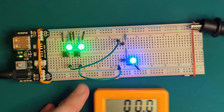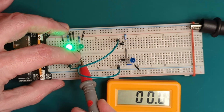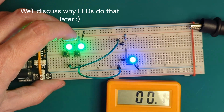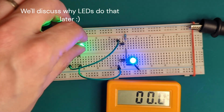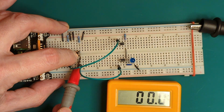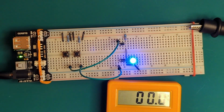If we measure the inputs, now they should be cleaner. So that's 0 volts, and that's still not 5 volts, and that's because the LED is kind of interfering with this result. So I'll have to take them away still. Let me do that. So now we have 5 volts when this is released and 0 volts when this is pressed, which is what we want. And the gate still seems to work the proper way.